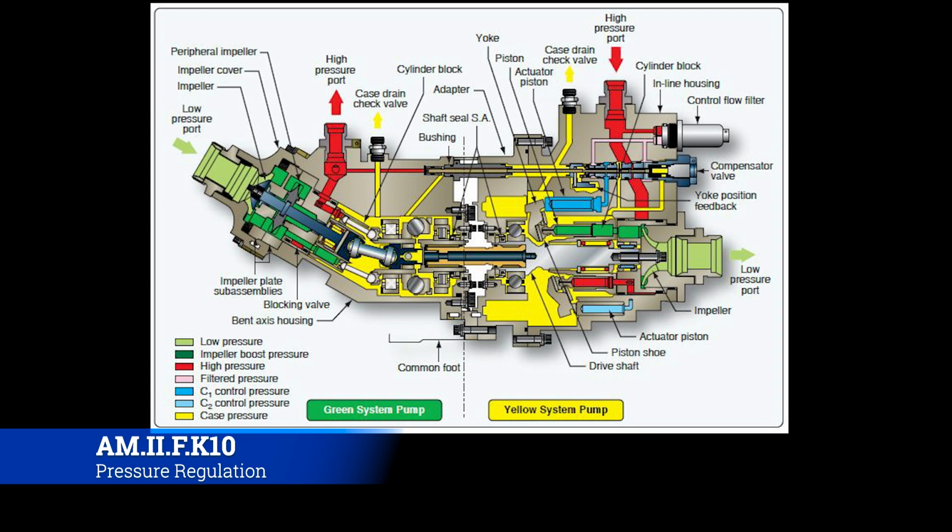And so, anyways, what the PTU does is that it will transfer power, but it won't transfer fluid. So you have independent hydraulic systems, which gives you a certain amount of redundancy. If there's a leak in one, you will be able to power the other system with another system without having to compromise or mix or mingle hydraulic fluids.